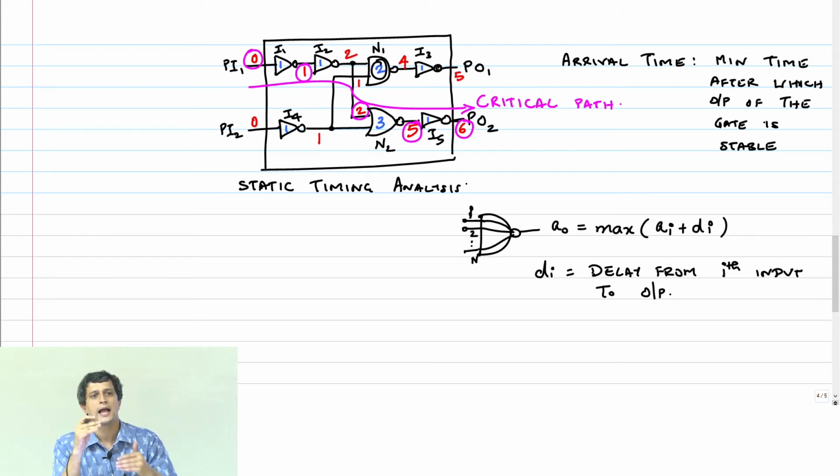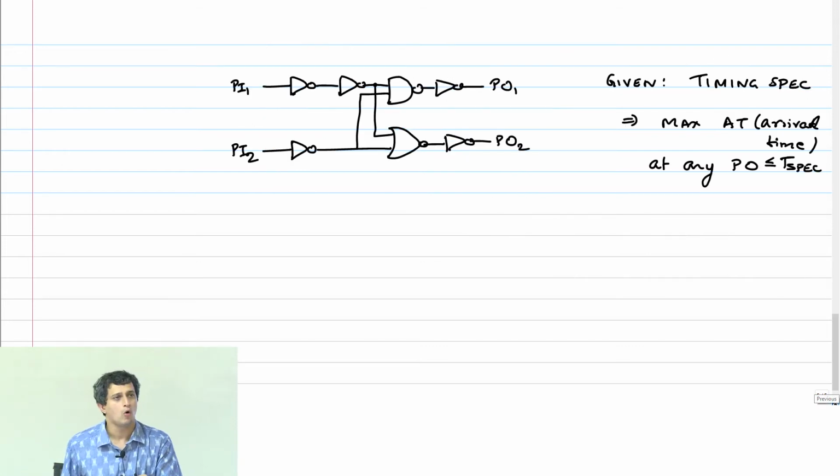You get it? So if I have a NAND gate with the input always tied to 0, the output will be 1. The input switching on the other thing is not going to affect the output. Right? Therefore, if I say that the output of that NAND gate is going to depend on the input which is always connected to 0, it doesn't make sense. But we are still considering those as well. Worst case timing analysis is what we are doing in static timing analysis. This is called STA.